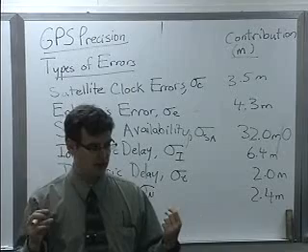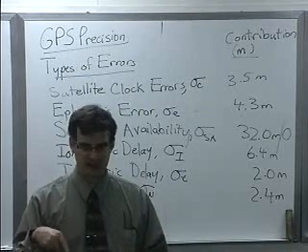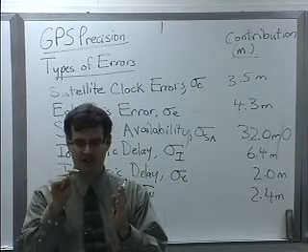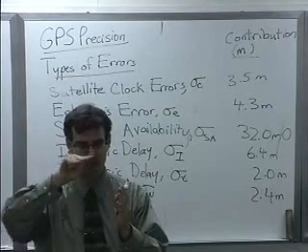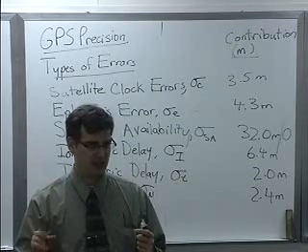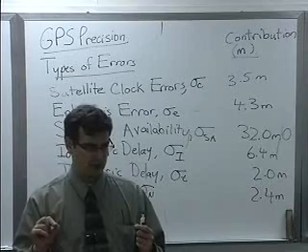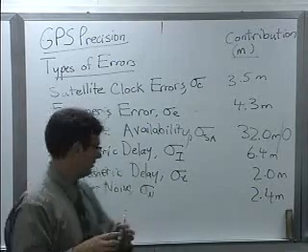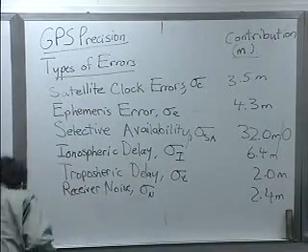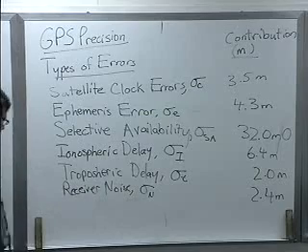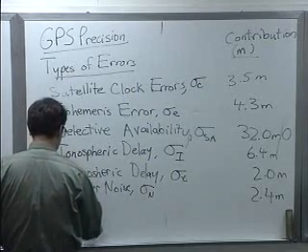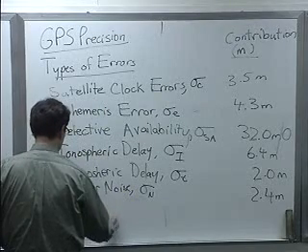So one of the things you have to do is not just look at what bin that chip is arriving in, but you have to look at the correlation peak, exactly where it occurs. And that's actually a very difficult measurement to make unless you have a very clean channel. So we'll see there's actually a signal-to-noise ratio dependency on this receiver noise figure.